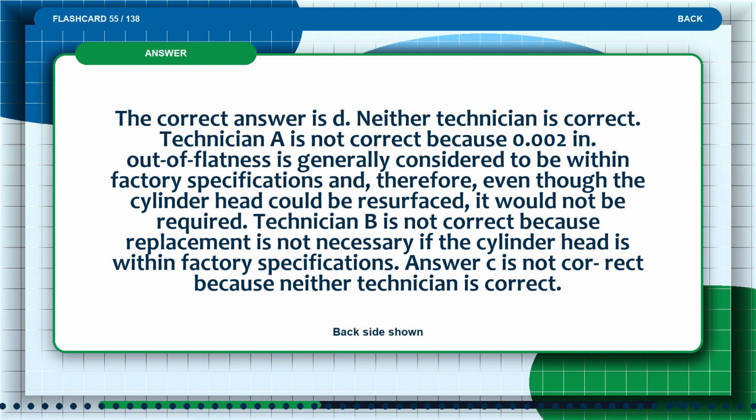The correct answer is D. Neither technician is correct. Technician A is not correct because 0.002 inches out of flatness is generally considered to be within factory specifications and, therefore, even though the cylinder head could be resurfaced, it would not be required. Technician B is not correct because replacement is not necessary if the cylinder head is within factory specifications. Answer C is not correct because neither technician is correct.